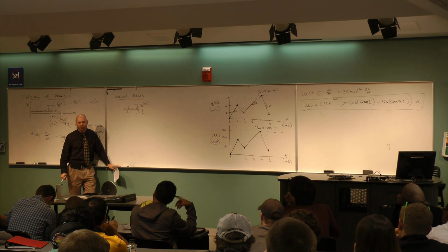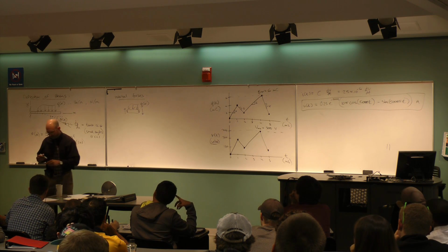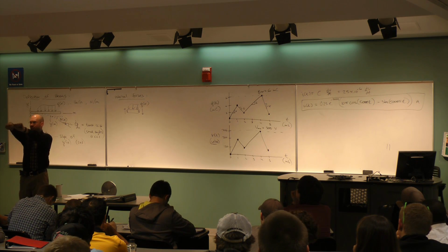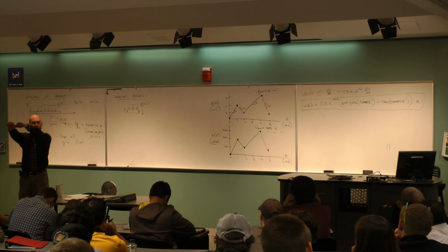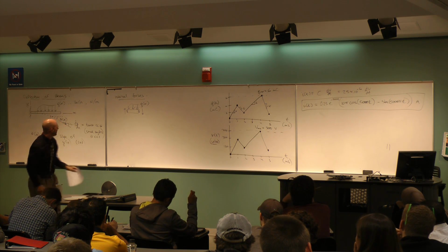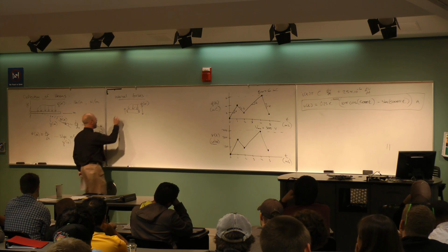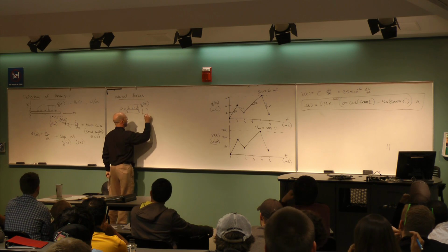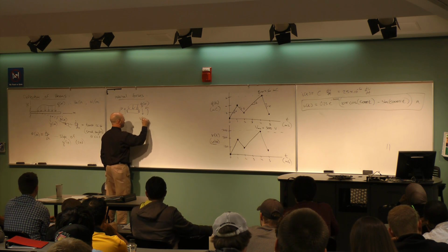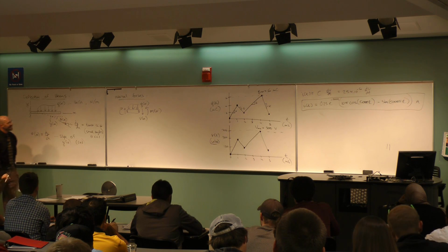In mechanics and materials, we don't call those torques. Torques, for us in engineering, are twisting moments like this, when I twist something. So we'll talk a little more about twisting next time, give you a homework problem on that. So this isn't twisting, this is bending things into a circle. So I can have internal things that look like this. So a shear force V, a bending moment M, okay?